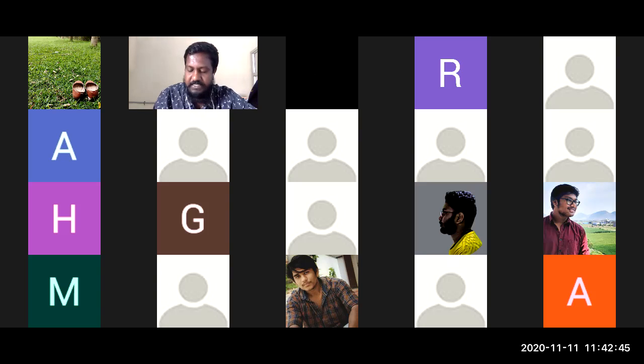Guys, were you all able to understand? The important things you need to understand from today's session are conductivity, the K value; resistivity, which is the inverse of conductivity; how to calculate conductance for a multi-layered body; and finally transmittance, the U value. These are parameters you need to know theoretically, just as knowledge.